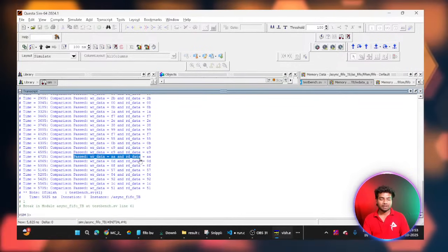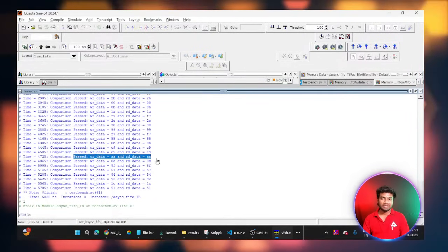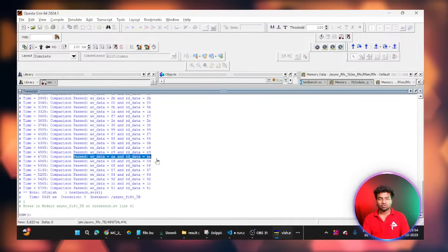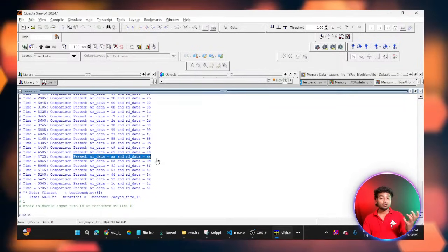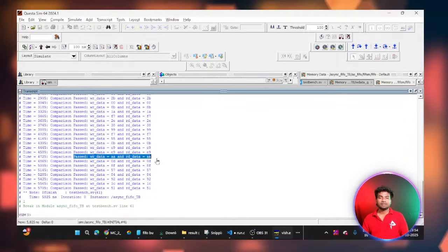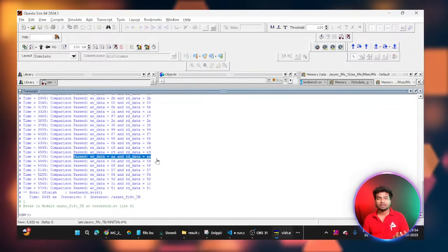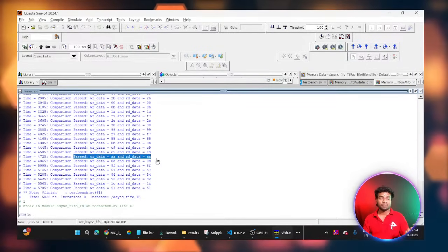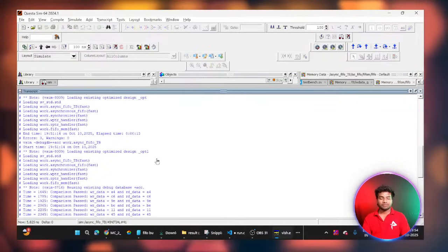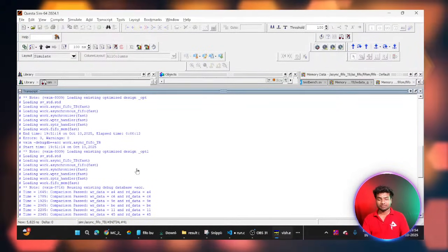So write data and read data are the same. It means I am getting the correct output value that I wrote into the FIFO buffer. So both different clock domains, system A and system B, are working fine. There is no data corruption or data error while transferring data between the two clock domains. This is how the FIFO synchronizer works for different clock domains.